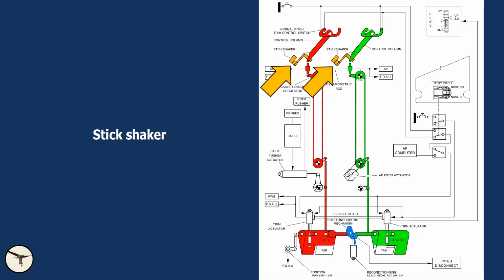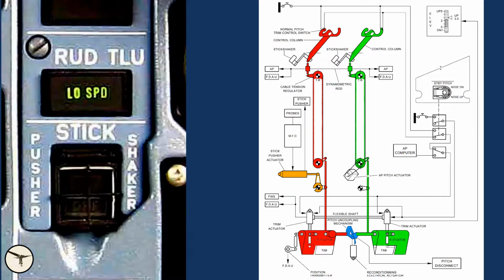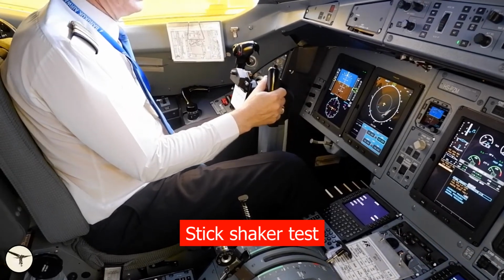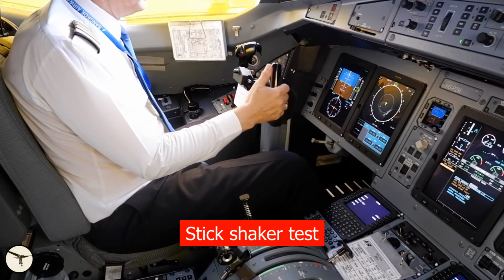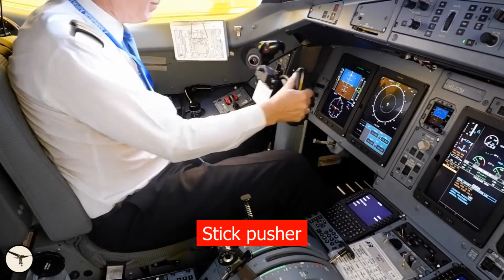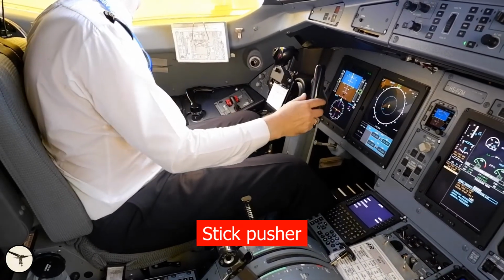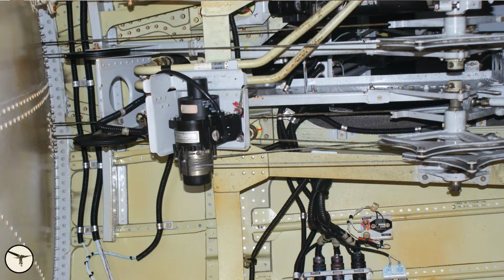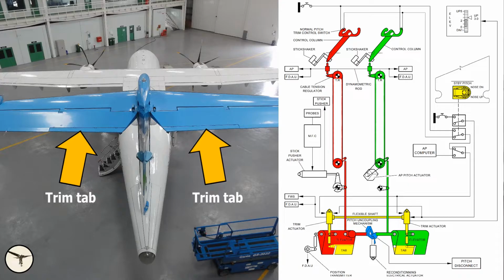A stick shaker is attached to the base of each control column. A stick pusher is attached to the captain's elevator channel. The stick pusher and shaker system can be disengaged with this push button. The autopilot pitch actuator is attached to the first officer's elevator channel via a bell crank. In addition, the autopilot also acts on the pitch trim.